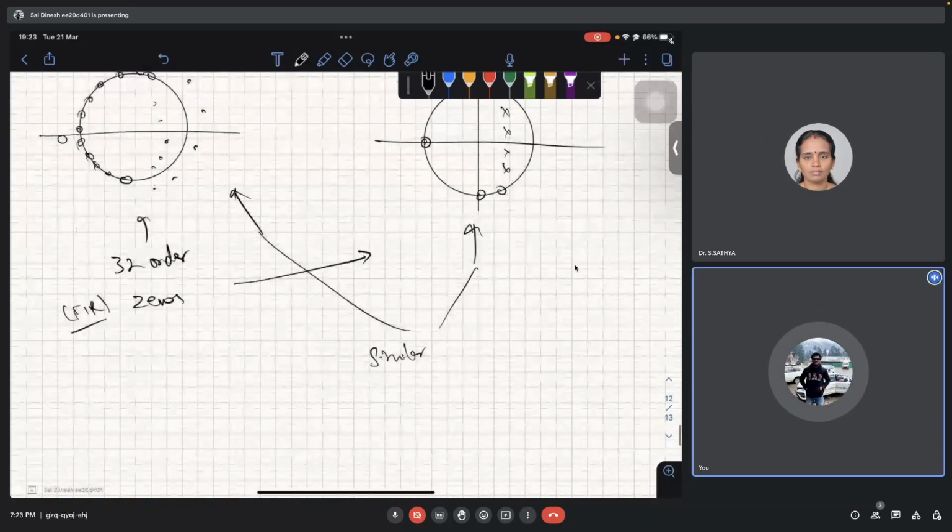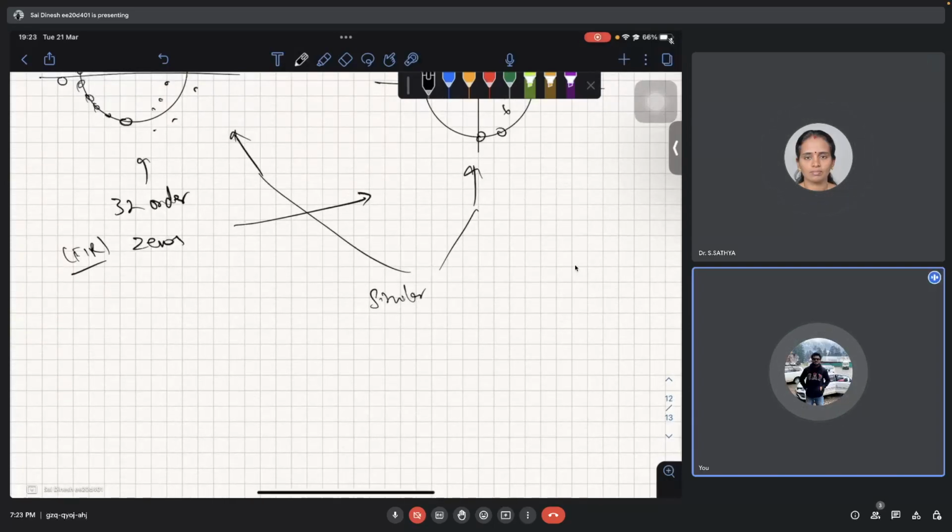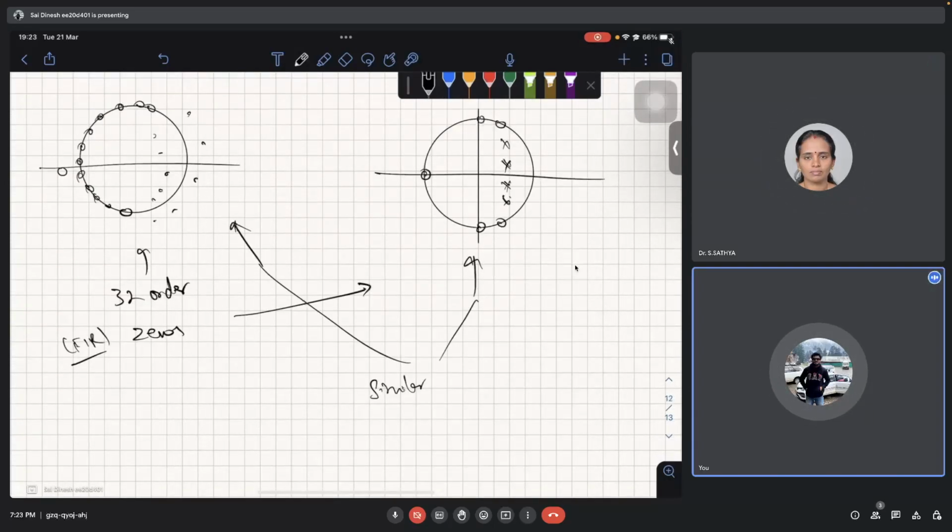So this is basically a low pass filter, right? What the poles give here is the enhancement of the gain. Whenever there is a pole, we know that there is a gain at that particular frequency. That is the really nice concept. If you can add poles, then we are getting a gain here. This is a 32 order system, and this is just 5 zeros and 4 poles basically. This is an IIR system, and this is an FIR system. These are some really nice and interesting topics that we can learn from Z transforms.